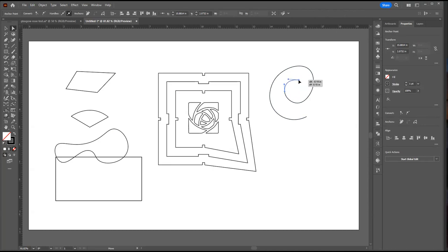But as we mentioned before, you can actually do something like bring it here. And then now we have that handle. Another nice thing about the A arrow, the white arrow, is that you can grab handles and move them. So it's not quite the same as the handle tool because that'll actually clear them out. But here you can say, okay, I move that. And now I change the angle just a little bit. And this is now a nicer spiral because of it.